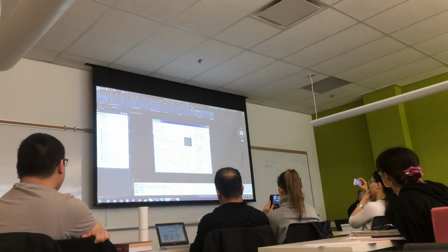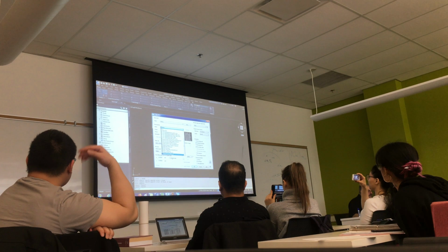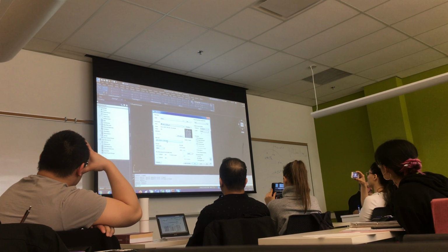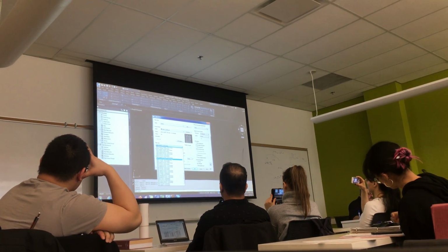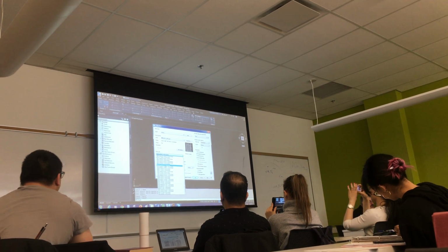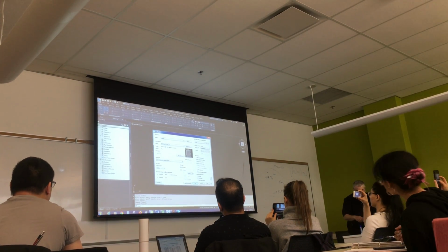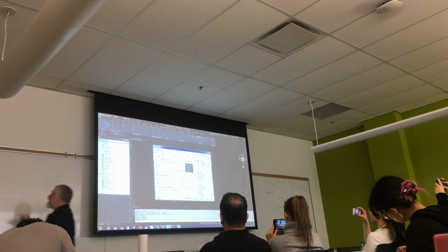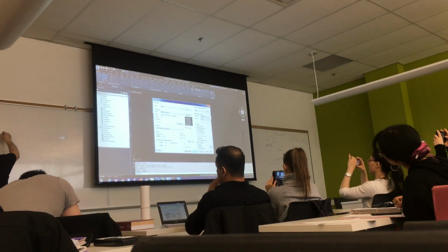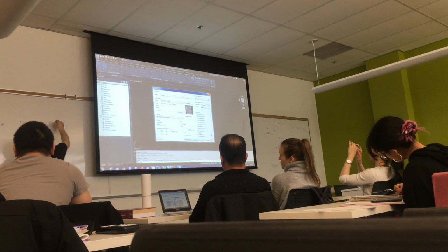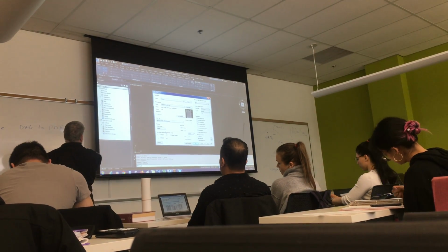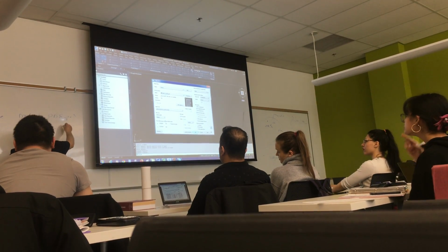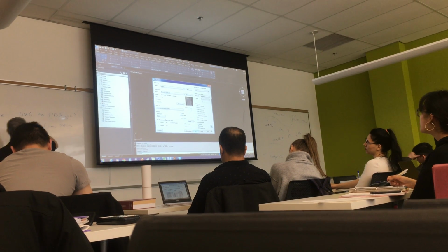If I go to plot, the device you should use is right here, DWG to PDF. It's the third one from the bottom. The paper size you want is 24 by 36, standard engineering size, 2 by 3 foot. So let me put some notes on the board. The plot device is DWG to PDF, and the file extension is PC3. This is third from bottom, typically. If you're looking for it, it's near the bottom of the list.